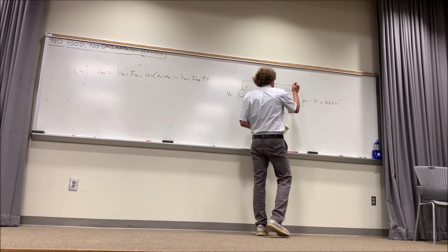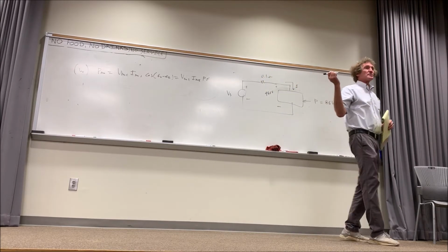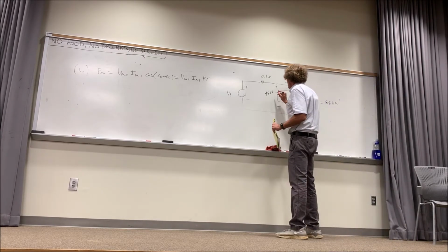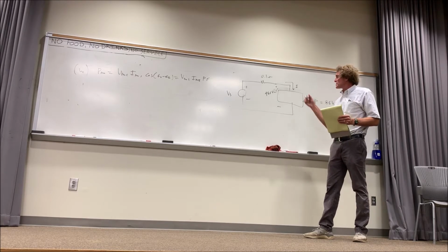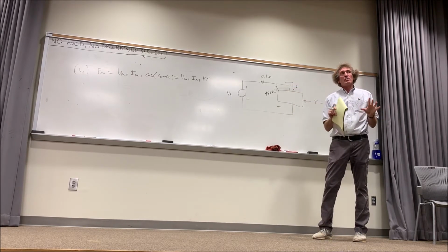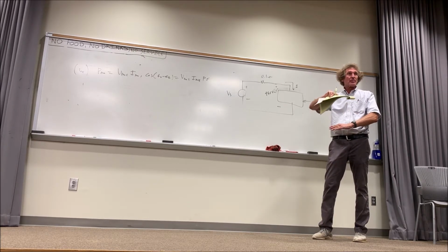I know what I really need is the current, don't I? Because if I have that current, I can get that voltage. Do y'all agree with me? Now, the 480 here is always assumed at 0 degrees, unless stated otherwise. You always assume this is the line voltage, just like the 117 or 120 would be assumed at 0 degrees, unless somebody would blatantly say that it wasn't. That's considered the reference voltage.